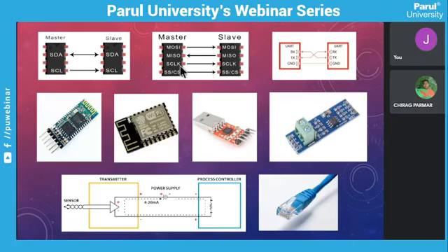Then there is a clock pin. The master clocks the slave. And then there is a separate pin allocated for selecting slaves. In SPI you can also include many slave devices with each other. Many of them can be included, and a dedicated pin is given to each of them. Through this pin, a dedicated unique ID is pulsed, and the slave which has that unique ID responds to that unique pulse. So that's the SPI, and it's quite fast compared to I2C.